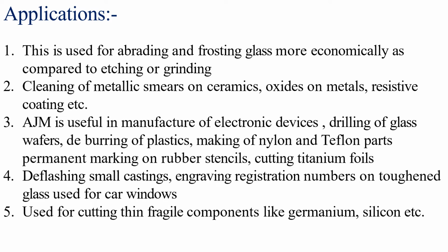Next, applications. It is used for abrading and frosting glass more economically as compared to etching or grinding. Cleaning of metallic smears or ceramics, oxides on metals, resistive coating, etc. Abrasive jet machining is useful in manufacturing of electronic devices, drilling of glass wafers, deburring of plastics, making of nylon and Teflon parts, making markings on rubber, stencils, cutting titanium foils, and removing small castings, and engraving registration numbers on toughened glass used for car windows.